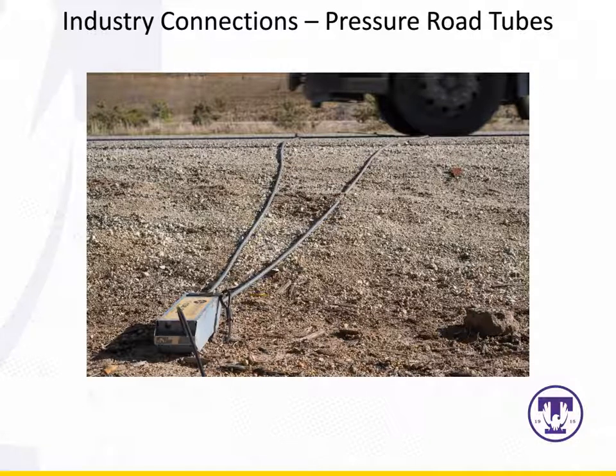And then over here there's a second one, so that when the wheels hit this tube, they know how long it took to go from point A to point B. If you know how far apart that is, and you know how long it took, you can easily know how fast they were going. So this helps in a lot of ways. Specifically, this is used for traffic counting, for city planning, things like that.